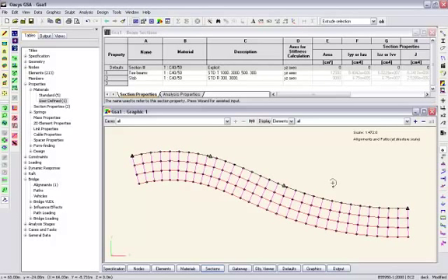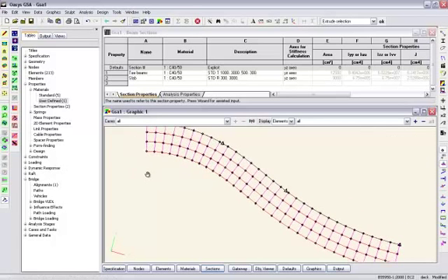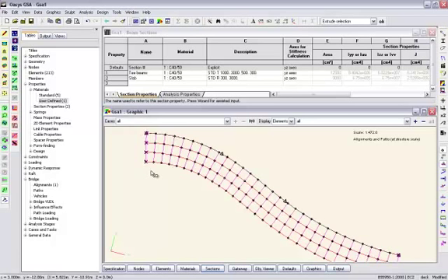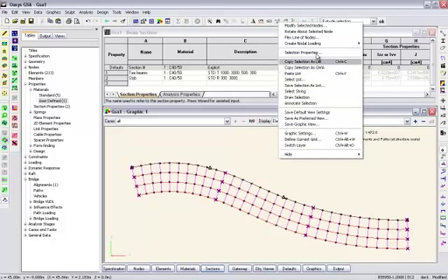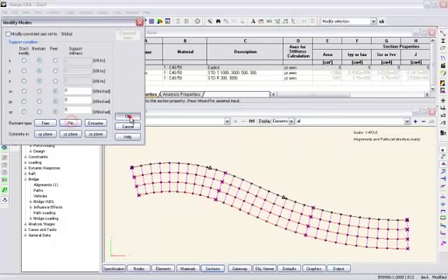Now, we need to create some support points. I'm going to pin at the end. I use the keyboard to rotate the view a bit, to make it easier to select. And then on third points, so 1, 2, 3, 4, 5, 6, 7, 8, 9, 10, and 1, 2, 3, 4, 5, 6, 7, 8, 9, 10. So third points, modify those and pin them.